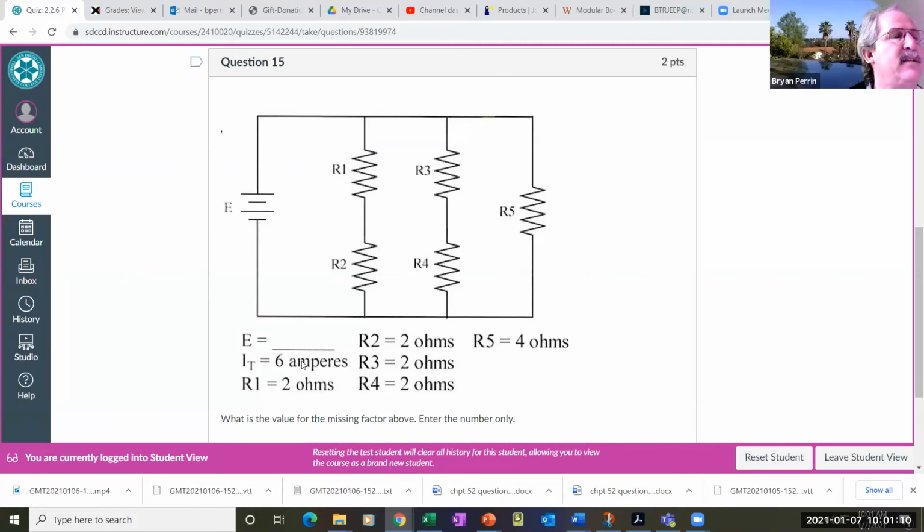And if I take that times 6, I come up with 7.98, or basically 8 volts. And if I put 8 volts in here, you'll find that it works. But that's how we get there using the formula. The other way would have been to plug in a 12 volt. Does that work? No, it's too big. I can plug in a 6 volt. Nope, that's too small. It has to be in between. And I can do that, but the formula just gets you right there.